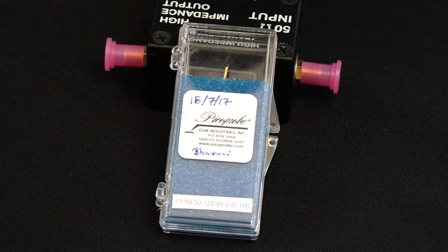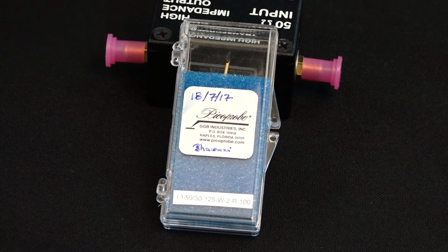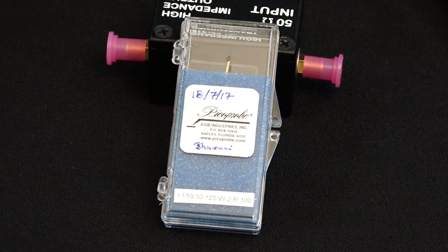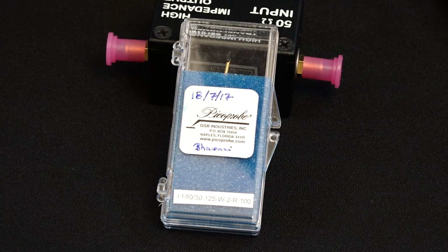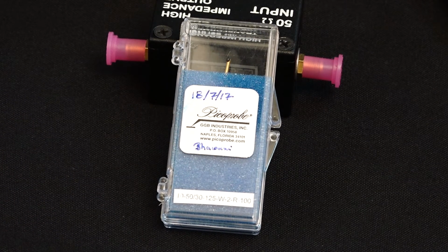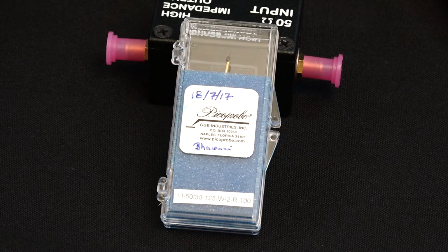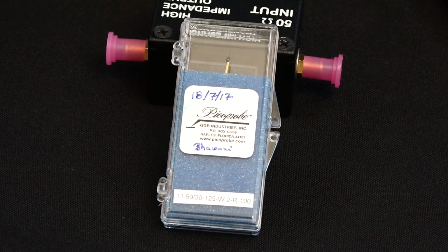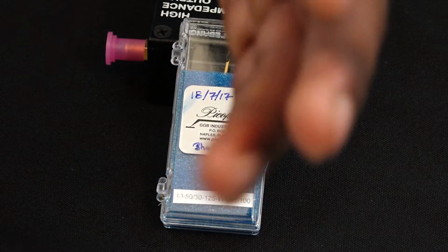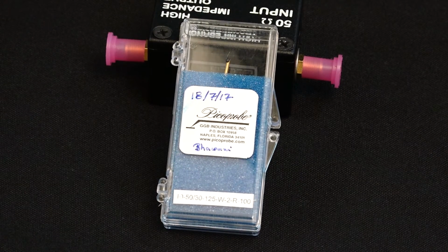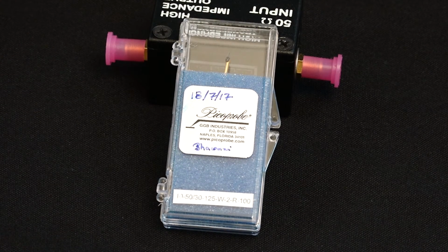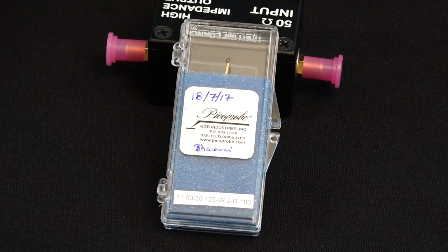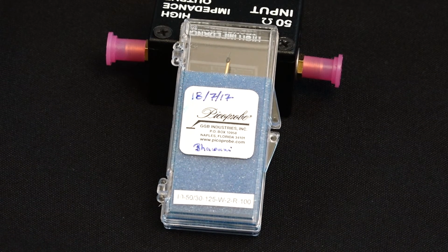I told you that they have 2 pins here. One is for signal and one is for the ground. The R here signifies which of the 2 pins is actually the ground. When you look at this probe tip directly face to face, so the pins would be facing you and you would be facing the pins, the pin on your right hand side would be the pin that is ground. The other pin would be signal.